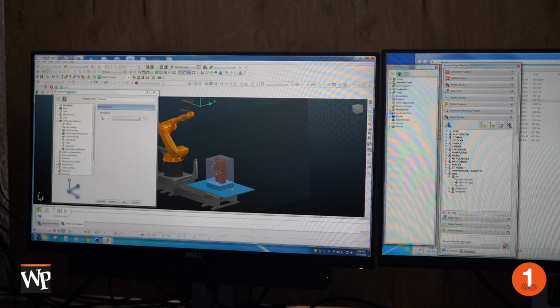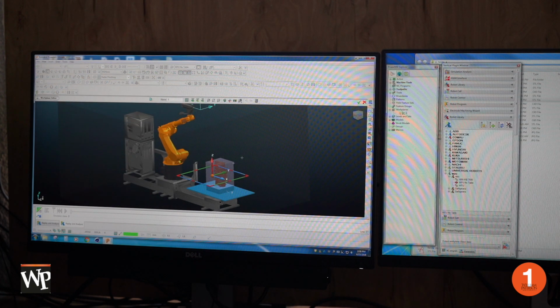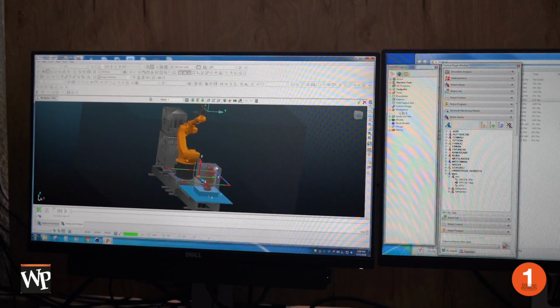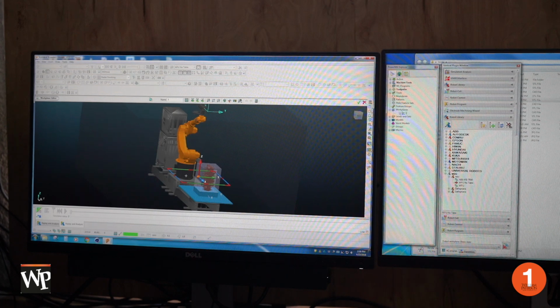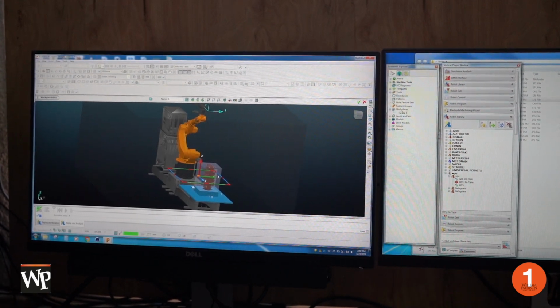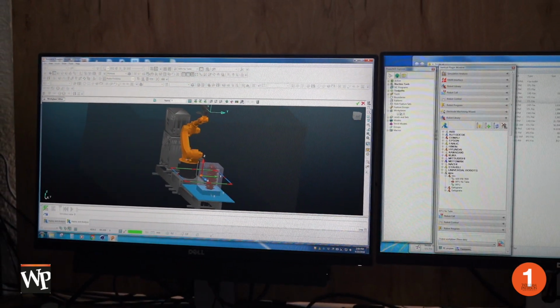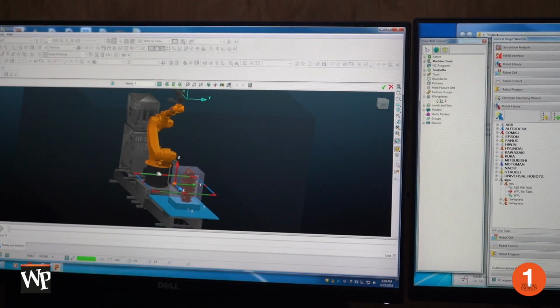So I'm going to hit the plus sign and click on our first work plane, and I'm going to go to work plane editor. So yeah, see our Z is vertical. We want to come into this model not at 90 degrees, because then we still have the chance of hitting our bed, but somewhere in between these.